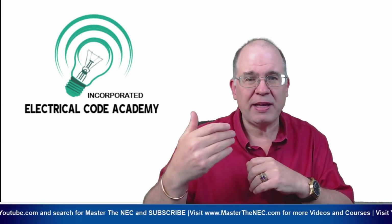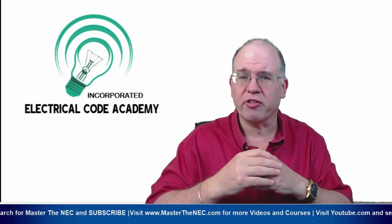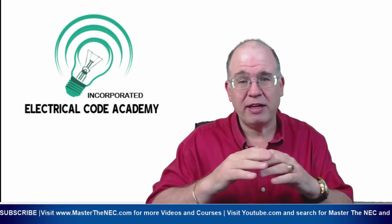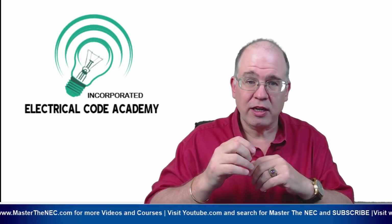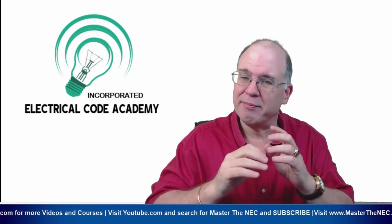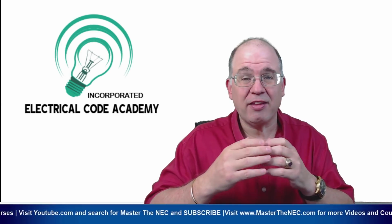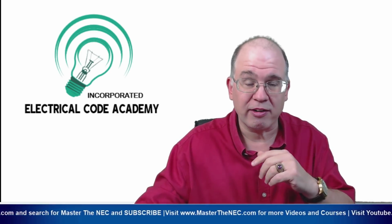Now, the code is telling me I have to size something, whether it's the overcurrent device or I have to compare two sizes for conductor sizing to consider the continuous load. But when we're talking about the load, just remember, the load is the load. That's going to be an important thing to remember when we start sizing conductors in 210.19(A)(1)(b). Don't need to worry about that yet, but you have to remember that nothing changes the load. Now, the condition of use might affect it, but at the end of the day, the load is the load. Remember that. That's going to serve you well here in this module.